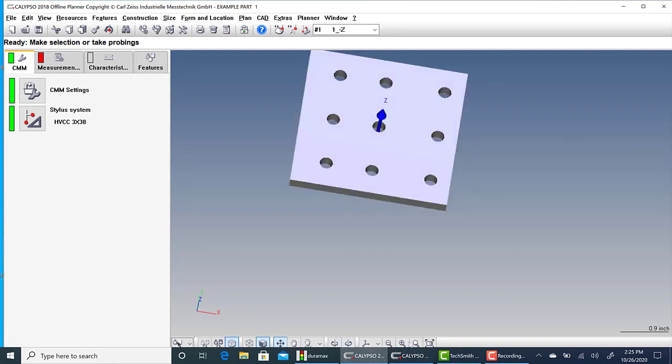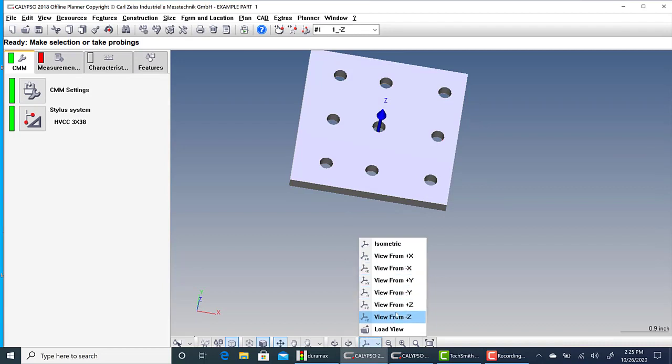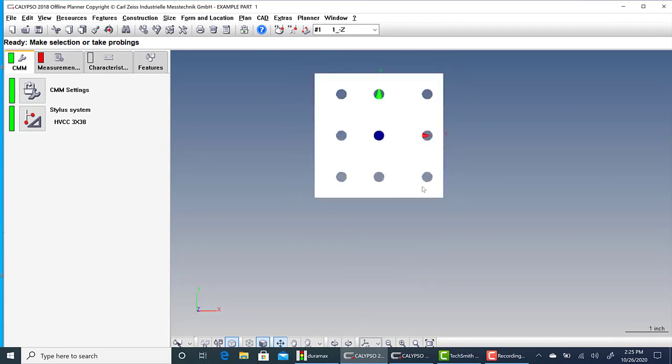let's just go to the top view here from Z Plus. If you're kicked, let's say like that a little bit, and you're out at a clocking this way, the machine will square it up in the program and align itself. Okay, as long as you're not way out, the software goes to the part. The part does not necessarily go to the software, if that makes sense.